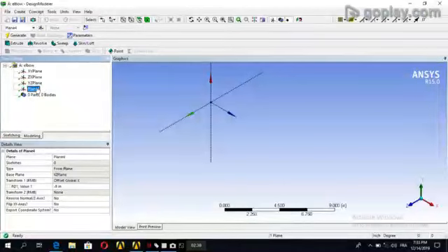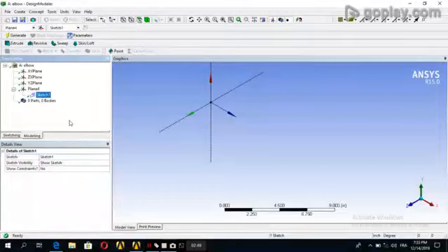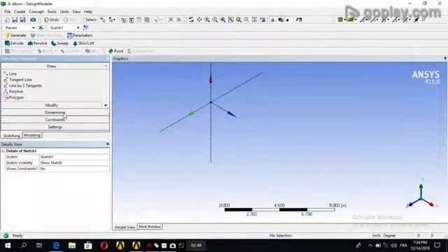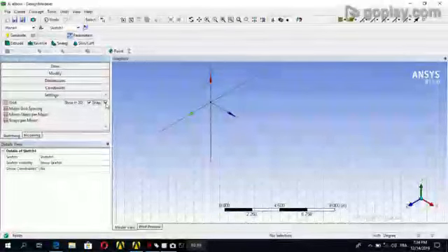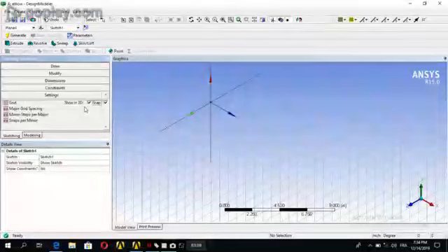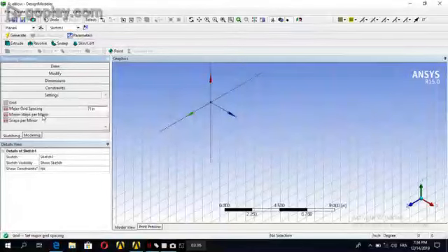Now we'll select plane 4, then new sketch, and there's the sketch 1 based on the plane 4. Now we will go to sketching, then settings, then grid, and enable show in 2D and snap, and set the major grid spacing to 1. It's already 1, and minor steps per major to 2.